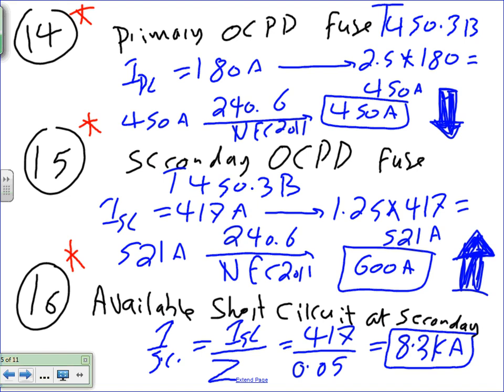And the voltage. What's the voltage? The voltage in the secondary is 208, so I need my circuit breakers to be rated for 208 or higher. Most likely they would be 300 or 600 volt rated circuit breakers. You're good to go. You see how important the short circuit and the full load are? Any questions, guys, about this?